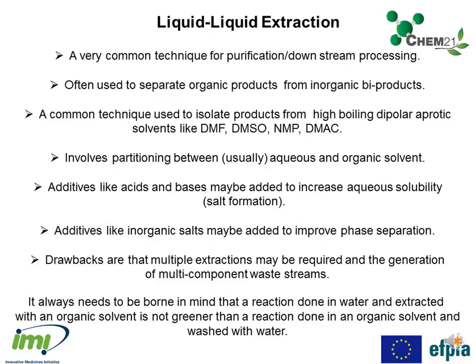Typically, additives like acids and bases may be added to increase aqueous solubility. So if we can form a salt, take it into water, wash it with a solvent, neutralize and recover by washing with another solvent. It's fairly typical. Additives like inorganic salts may be added to improve phase separation and reduce emulsions.